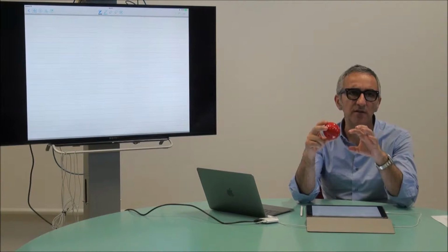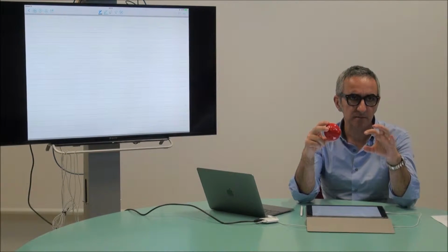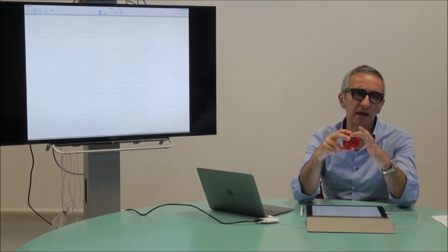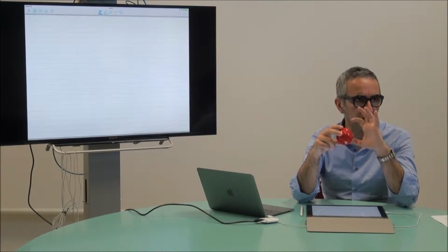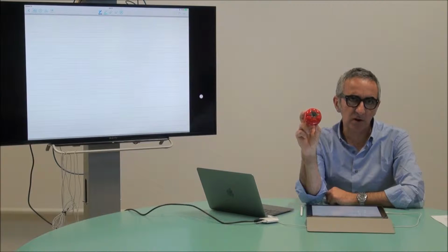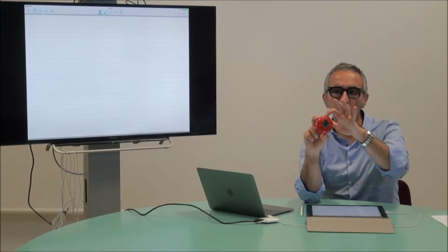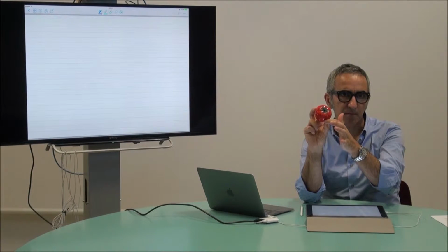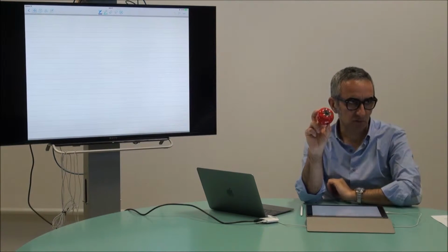So we assume that we have hard finger contact models, which means that at each contact point I can exchange only 3 force directions. In this case, where I have 3 contact points, I have 3 forces here, 3 forces here, and 3 forces here, that I can control.